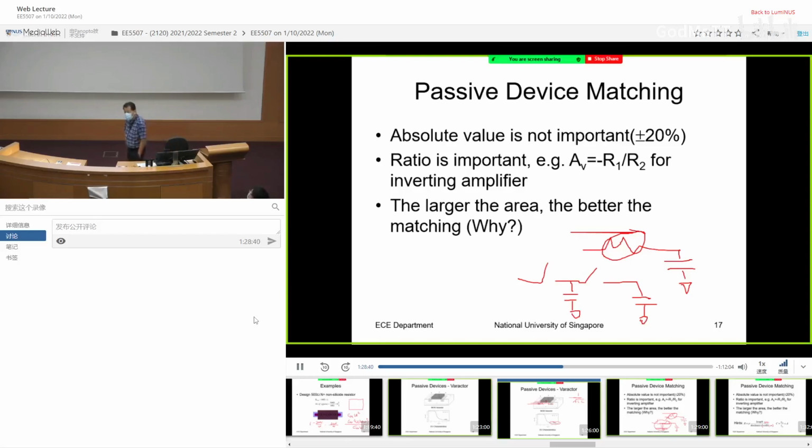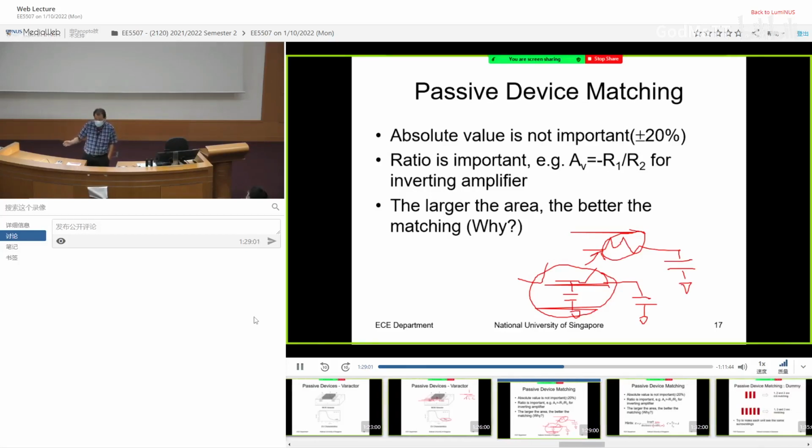Okay, something like that. This switch capacitor, this whole thing, can actually behave like a resistor. And the resistor value is related to the capacitor value and the time period. Time period is accurately controlled because in all digital circuits, you need an accurate clock. So the clock is accurate, and the resistor value depends on the capacitor. So when you look at the RC value, eventually you will see that it turns out to be a capacitor ratio. So for switch capacitor, in the end, the bandwidth depends on the two capacitor ratio. So the filter can also be accurately designed, the cutoff frequency.